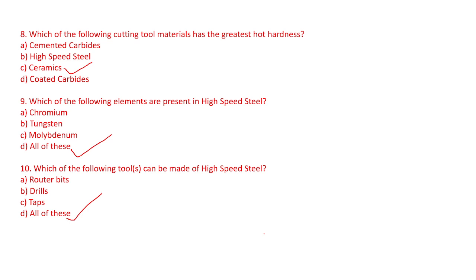There are SVJBL, SVJBR. Basically, the tool holders have got an ISO code, and the insert also has got a code. DNMG 040408 is an insert.